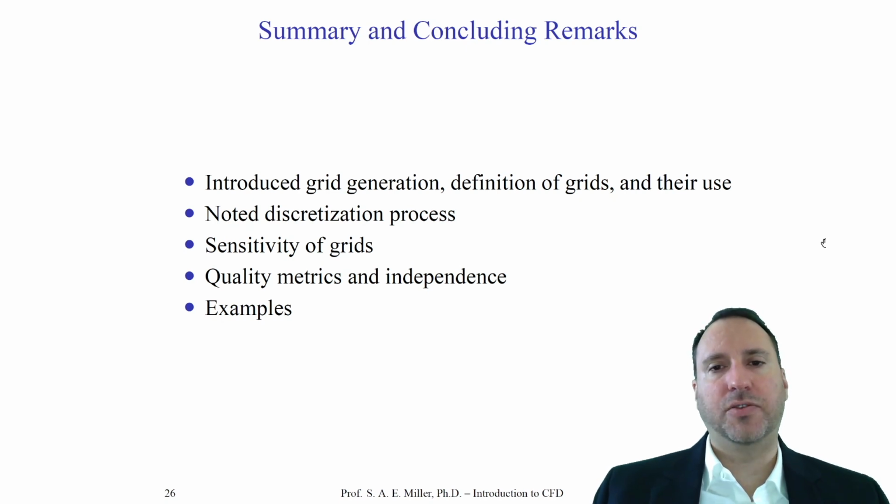We also define grids and what they are and how they're used. Remember, there's structured and unstructured grids. Those are the 2 major types. Structured grids do not have connectivity because it's implied. Unstructured grids do have connectivity, and they can exist of many types of elements. We talked a tiny bit, and for only a few minutes, of what a good computational domain looks like and what maybe a bad one is. You'll learn this through experience mostly only, but throughout this class we'll look at more examples.